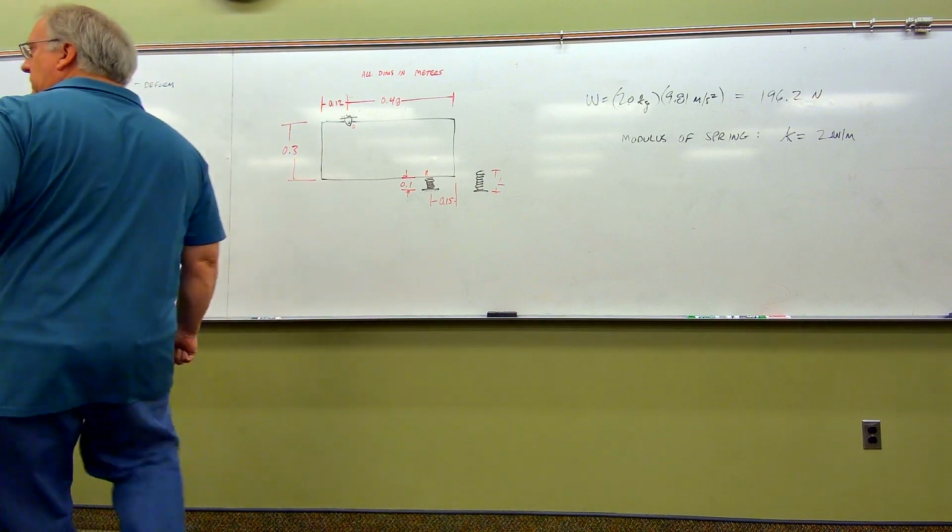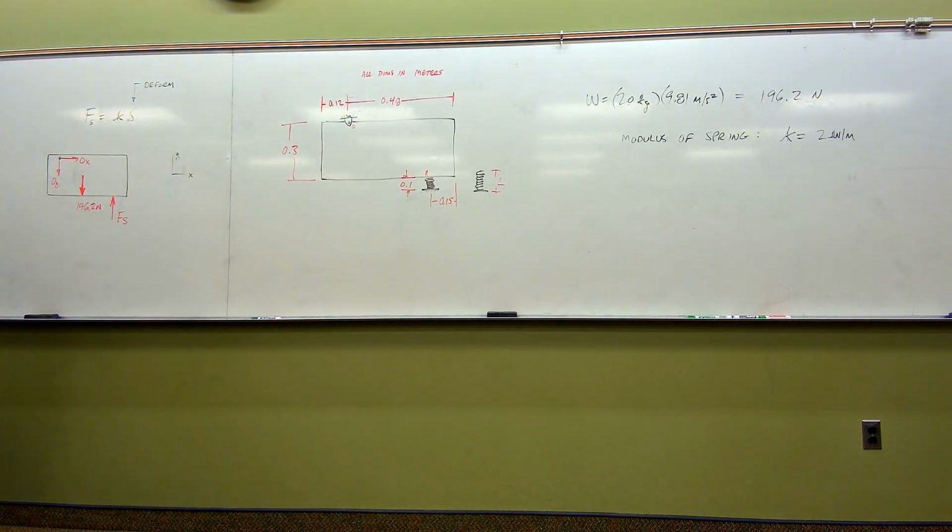Fantastic question, and there are two reasons for it. Number one is, springs we treat just like tension, like there's a rope there, but there's not a rope there. We treat those as singular forces right on their axis. So that's one reason not to. The other reason is, we assume that all surfaces are smooth. So in this case, if the spring was actually on this smooth surface and there's no friction here, there wouldn't be any force that way. So it's a great question. Any other questions about the free body before we move past it?